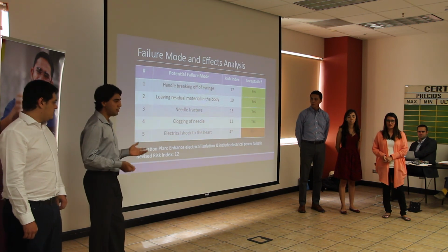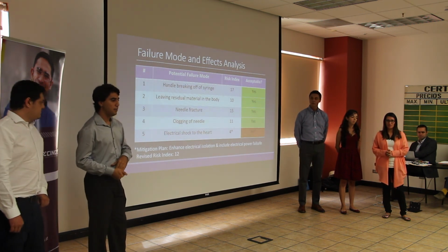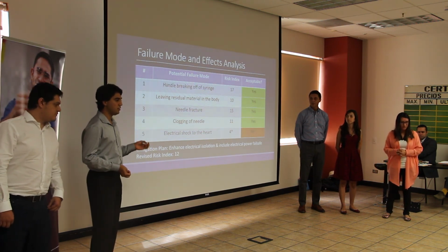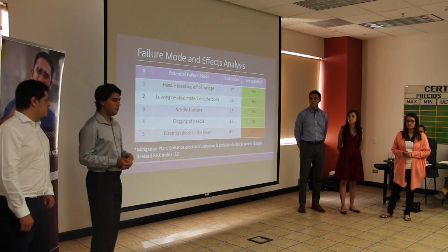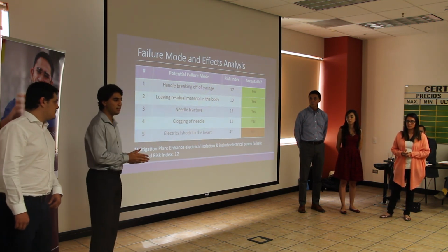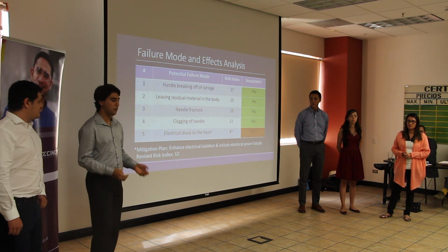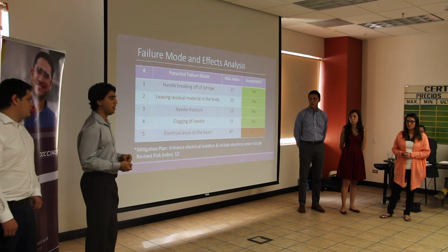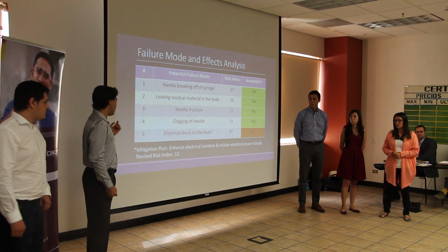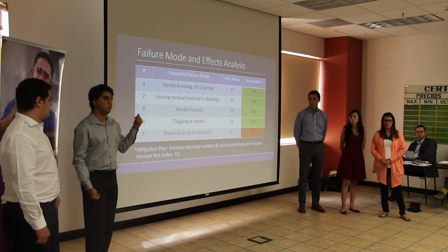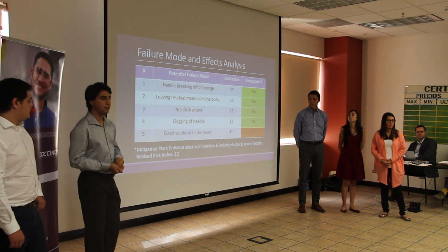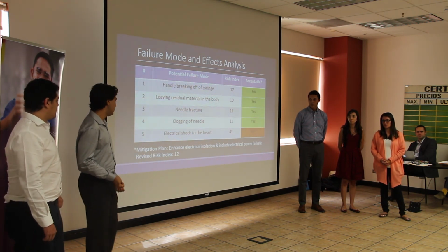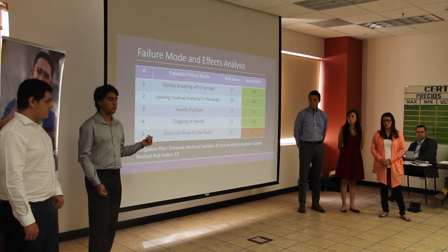To fix that, we will have to go again through the design process and really focus on electrical isolation and shielding, so that everything that's electrical is completely isolated and never makes contact with liquids or with other parts. We would design that well with high safety factors that allow us to raise that level to where we're certain that the probability of a shock occurring is improbable. That would give us a risk index of 12, which would be acceptable.